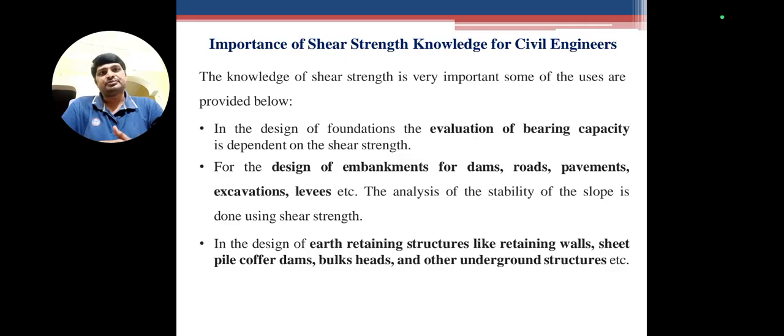What is the importance of shear strength knowledge for civil engineers? The knowledge of shear strength is very important. Some of the uses are provided below. In the design of foundations, evaluation of the bearing capacity is dependent upon the shear strength. For the design of embankments, dams, roads, pavements, excavations, levees, etc. In the design of earth retaining structures like retaining walls, sheet piles, cofferdams, bulkheads, and other underground structures.